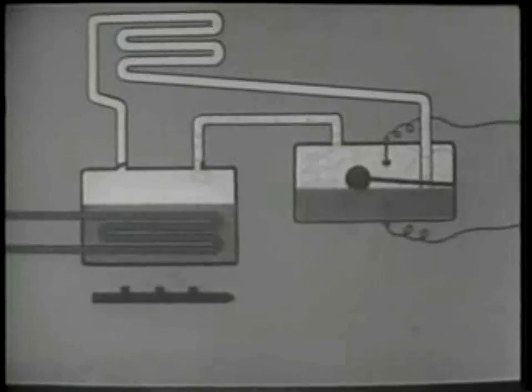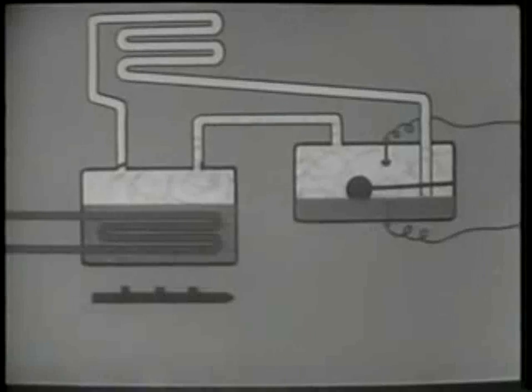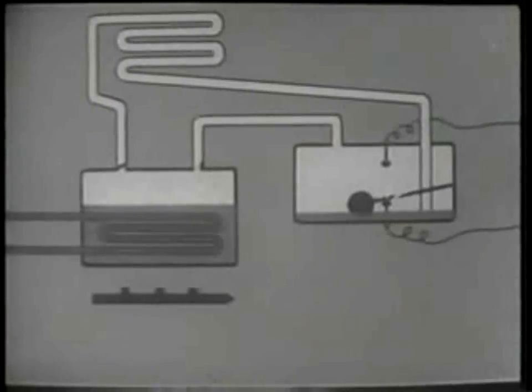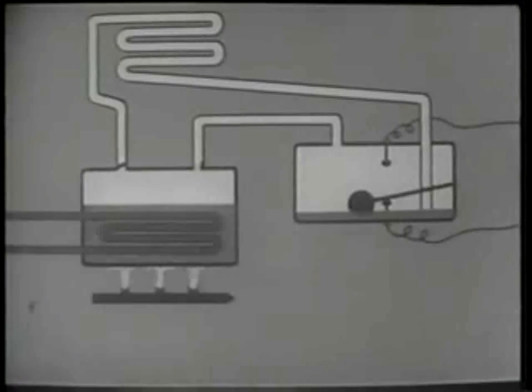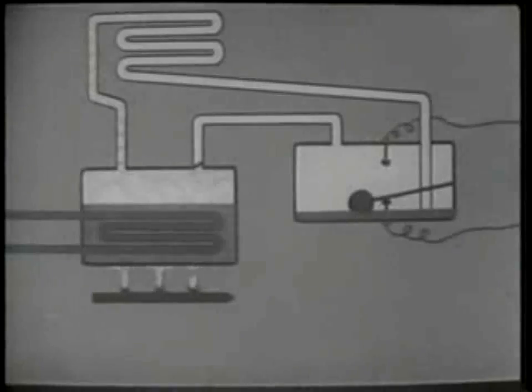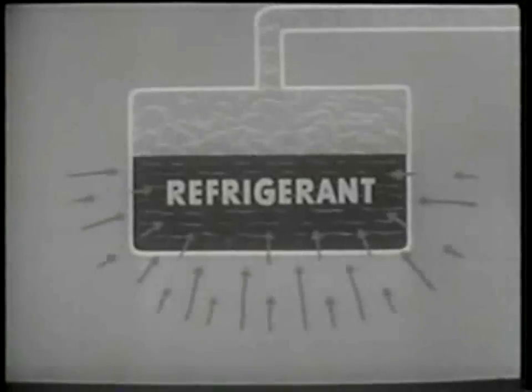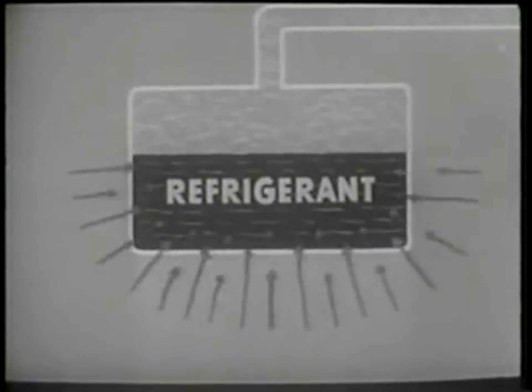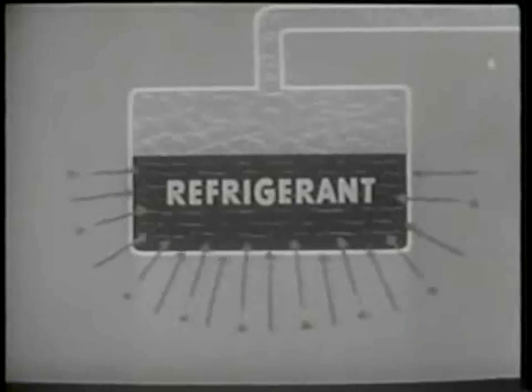The principles of refrigeration are physical principles applied as follows for the purpose of removing heat and reducing temperature. First, mechanical refrigeration rests on the ability of a refrigerant to absorb heat while changing from a liquid to a gas and to release that heat while returning to the liquid state. Second, when the pressure on a liquid refrigerant is reduced, the liquid boils at a lower temperature. Third, the transfer of heat from food items or other warm surroundings to a liquid refrigerant involves three processes: radiation, convection, and conduction.